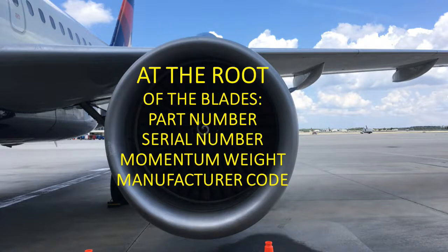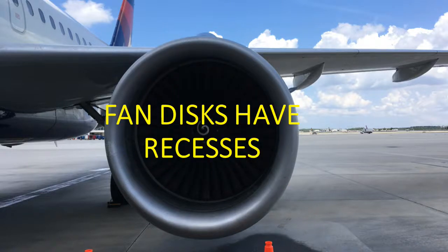Okay, all right, so it gives you an idea with the fan blades themselves. At the root of the fan blade you're going to see markings with information. It's going to show the part number, the serial number, the moment weight, and the manufacturer code. And that's important. Like I said, you don't want to just take a fan blade and it doesn't matter which blade. Those markings are there at the blade root. Of course, your fan disc has those recesses. Remember I said that I call them disc slots, but those are where you would actually put the blades in if you were in charge of installing those blades.